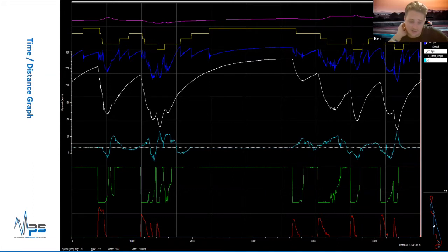Some things are obvious. With steering angle, you might only be able to go half a turn lock to lock, so minus 180 degrees to plus 180 degrees for steering wheel angle, and throttle can only really go from 0 to 100. But say speed, for example, or brake pressure, you have to go through your data and see what limits you're working within.